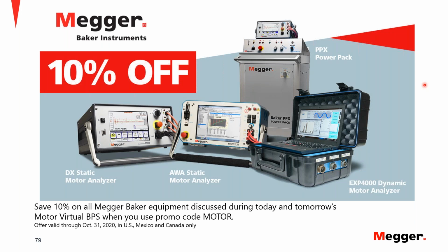But if you were going only on voltage, I would say you do the 2 plus 1000, so a 12, 13, 14, 15 kV machine should be able to test this motor, with the question being whether that machine has enough capacity to give you 15 kV with the frame that you have. So in order for me to answer that properly, I would need to know the power that motor has.